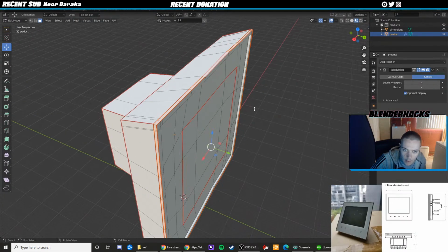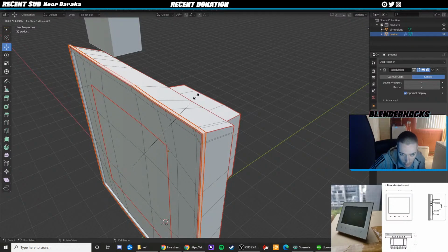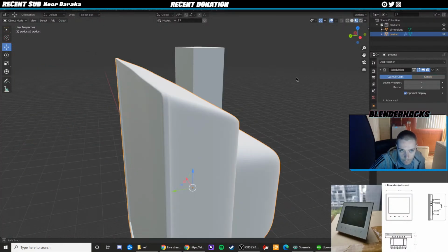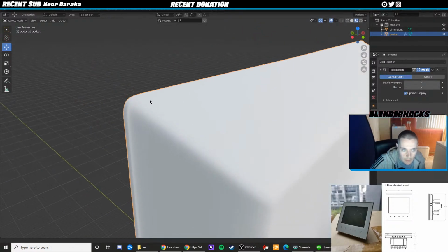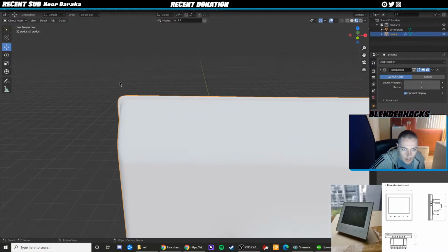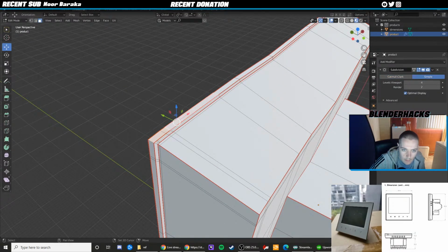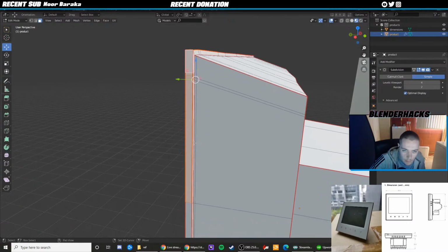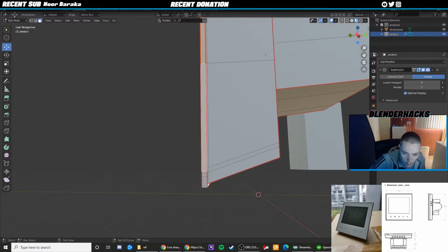Good luck with that. So we're going to re-extrude. So we're going to select all these faces on the edge. And press E again. This time we're going to press S to scale out. And as you can see now, if I add a bit more scaling, the extrusion is also coming out. If I add an edge here to tighten that up, it's coming out from these sides too. We can probably go back into here, select these again, which shows a better way to select these, but it kind of isn't. You just kind of have to deal with it.